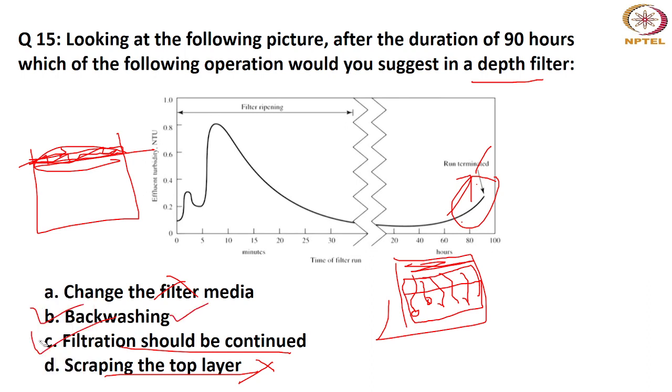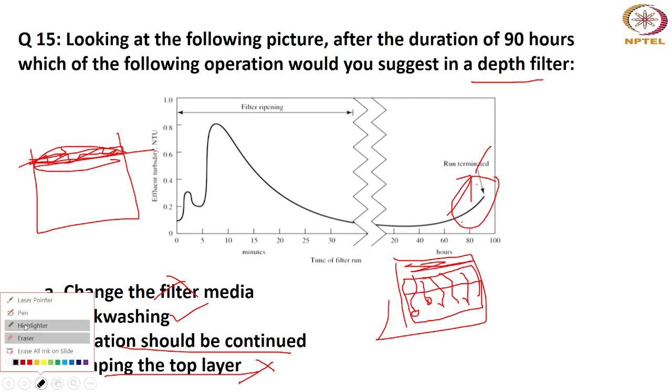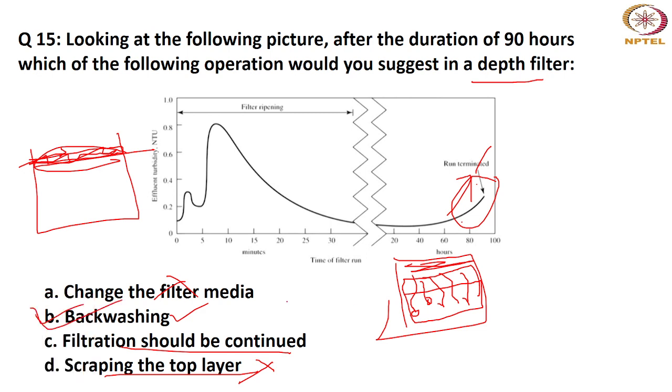Pardon, I'm erasing this. So I have only one option, that is backwashing. If you push the water from down below, it will wash all the impurities present at various depths of this filter.